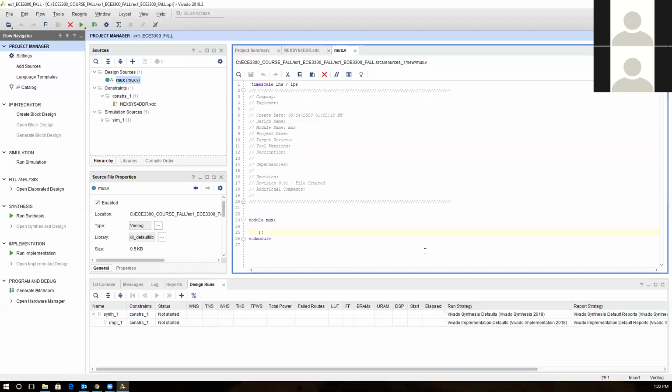So the hierarchy structure part of describing the file in Verilog, that file, we call it what? Module. And the module, when you write it, you have to call it module. The name of the module will be the name of the file. And then you will say module, and then you have the parentheses opening and closing for a reason.